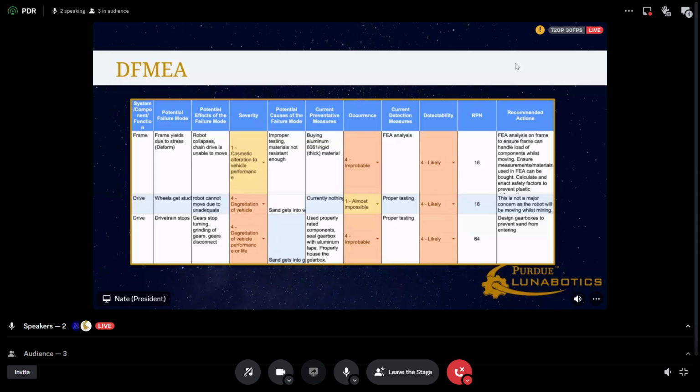Any small pieces that are subject to high stresses or strain are to be made of steel, and any bigger pieces are to be made out of 6061, and pieces not really prone to stress or strain are to be made with 6063 for making the components lighter.